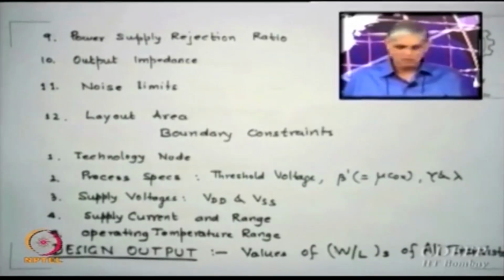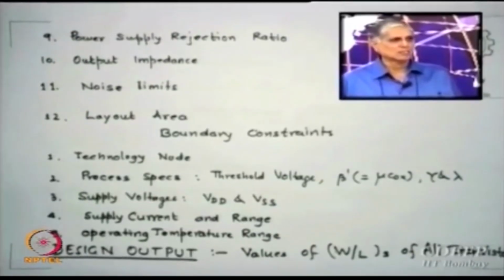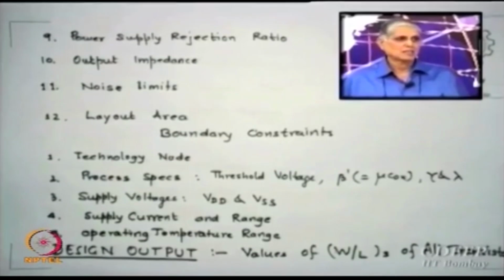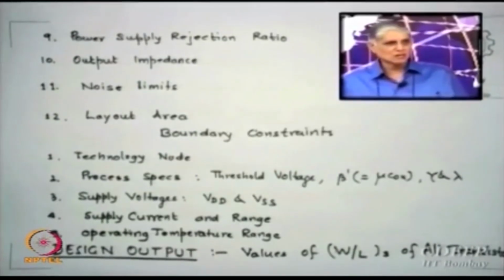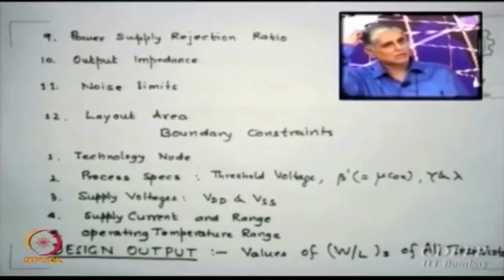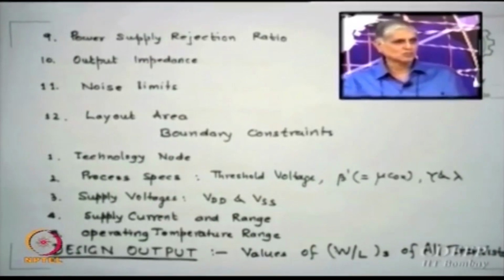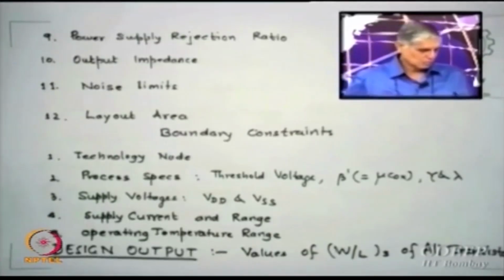As I said, typically my data from the books which I am using has a 0.8 micron SPICE data file. It does not mean that one cannot design at any other node. You need actual data from the SPICE file of whichever node you are using. Since I have copied it from the given book, which has a 0.8 SPICE file, I am just using it for my calculations.